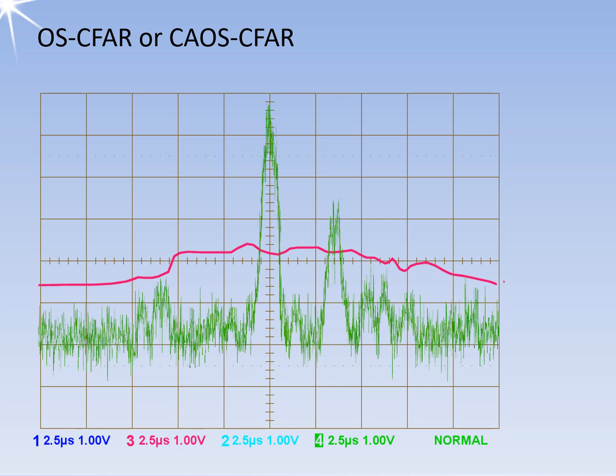Here, the duration of the calculation would not be so crucial if it were constant for each range cell. But sorting has a different computing time depending on the sequence of the data. This results in different processing times for neighboring cells, which is not allowed for real-time processing.